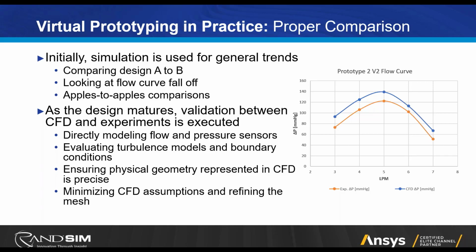So instead of just looking at the outlet pressure on a pump, we've actually modeled in a pressure tap into our CFD analysis so we can look at the pressure on the pressure tap like we would expect to see on the benchtop. So it's little changes like this, bringing our model a little bit closer to reality and mitigating the number of assumptions we're making in the CFD analysis, that really bring that validated data closer and closer to what you'd expect to see in the experiment.